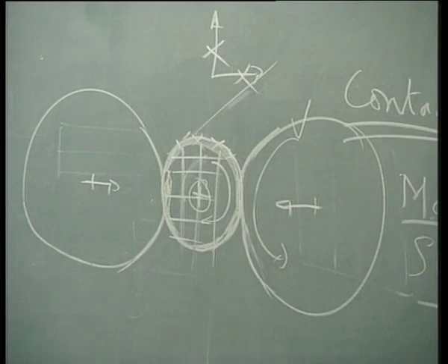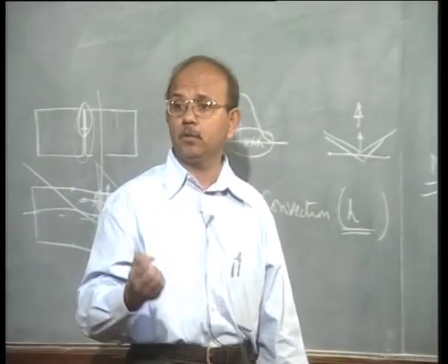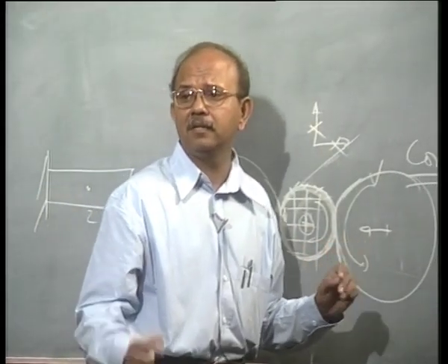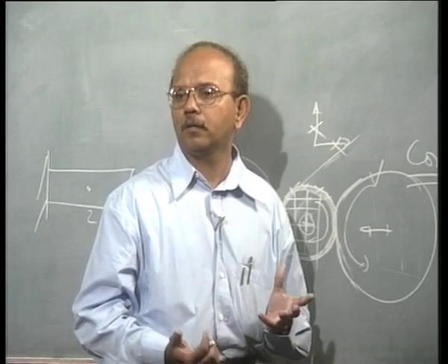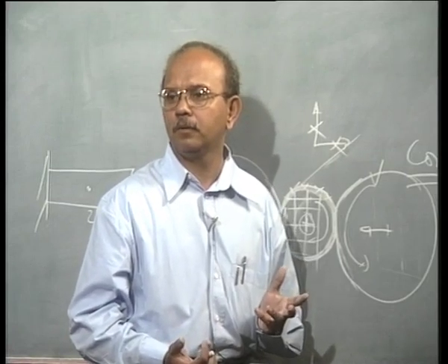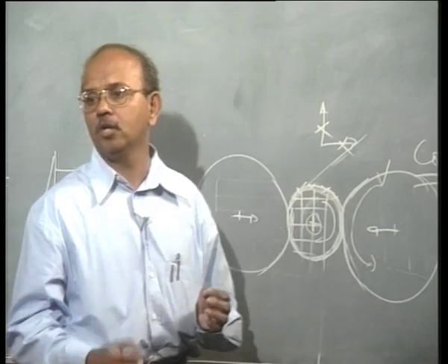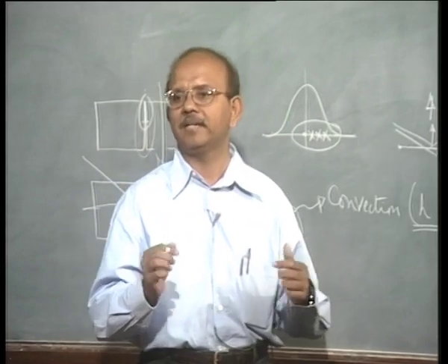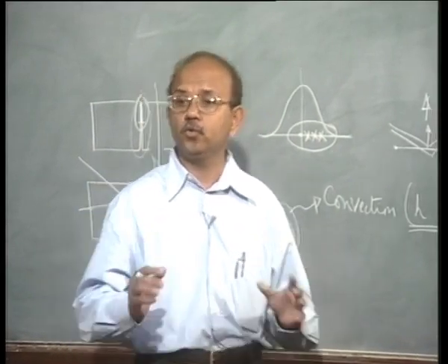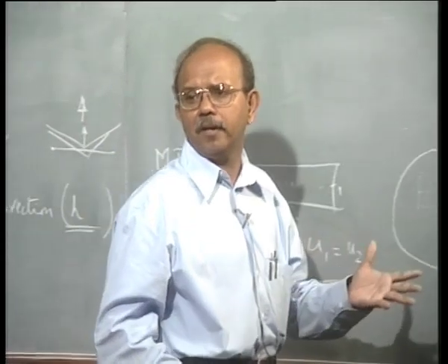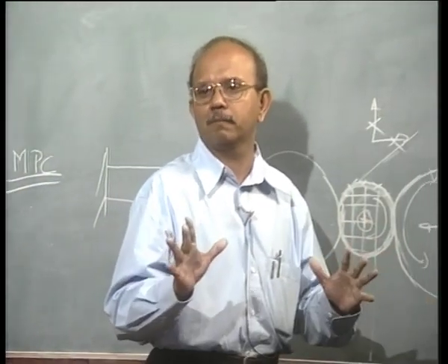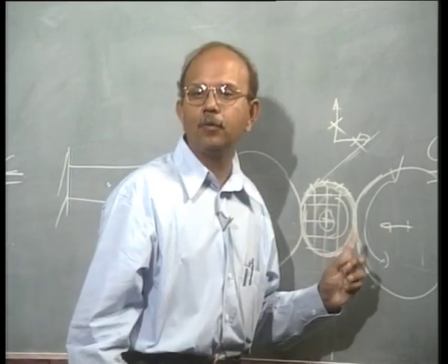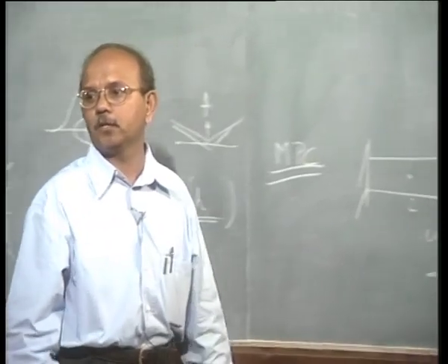Again you should look at whether it is going to rotate under my load or not. It is not that kind of issue, because the singularity is not removed by not applying a load in that direction. So you should say whatever be the load that is applied, it should not rotate. That is how you should look at it when you put a boundary condition. So when I fix this, I will have a problem because it will start rotating.